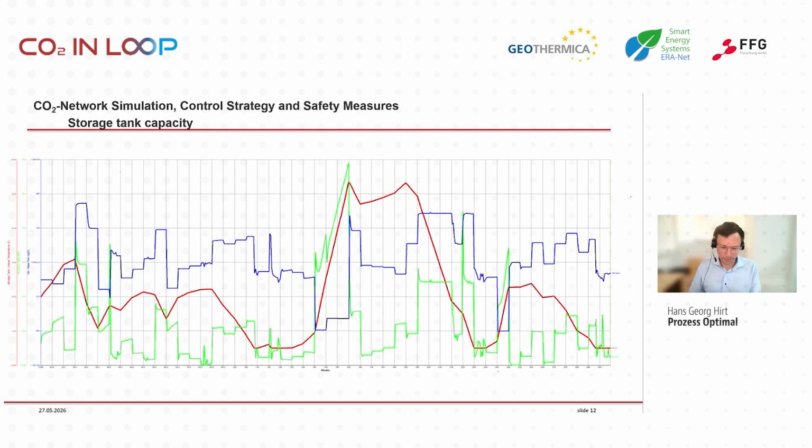And the buffer had a size of about 36 cubic meters, and it could be possible that the peak shaving could be even more with a bigger buffer, as you know. But in our operation, we tried to shave about the upper 10% of our end duties. And this was possible with this nearly 40 cubic meter buffer, operating between 5 degrees Celsius and 55 degrees Celsius in this propane heat pump of the energy store.